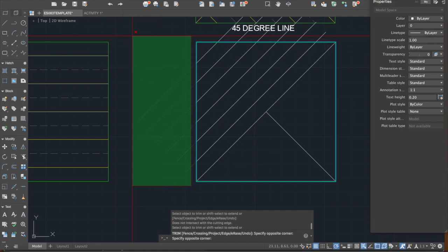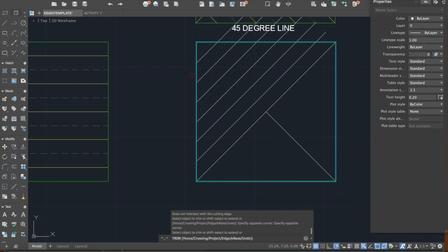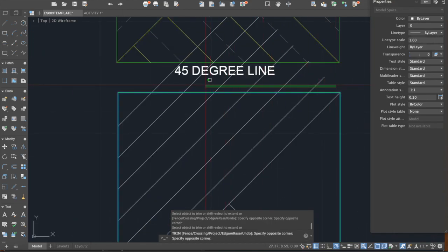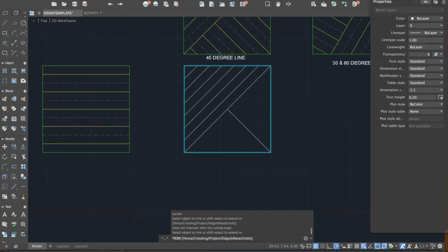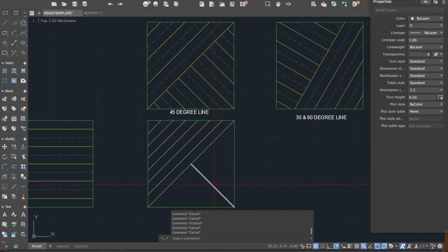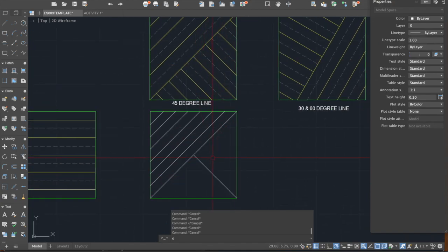As you can see, no, it will select the lines or the objects that were included in the selection. Same as here. So let's try this again, and then this time let's use the group selection, which is this one. Okay, so now we can proceed with the other direction, which is this one. So again, use offset, and then the distance is 0.5, 0.5, enter. So offset this line,